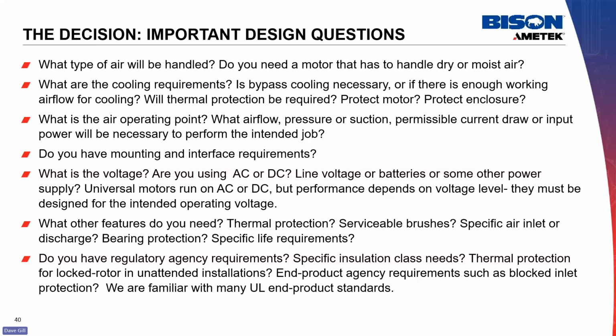Okay, what type of air will you be handling? Do you have to handle dry air or moist air? What are your cooling requirements? Do you need a bypass? Can you get by with the through flow? Will thermal protection be required? Is that to protect the motor or to protect your enclosure?